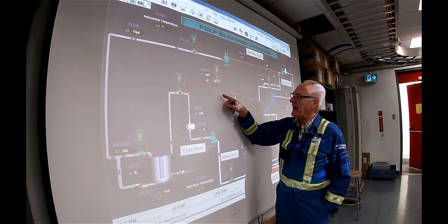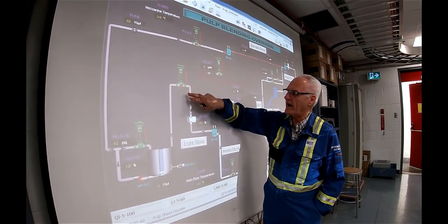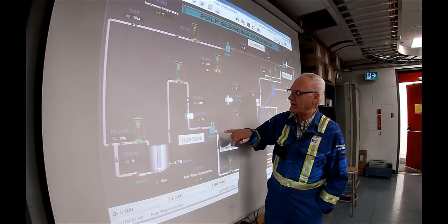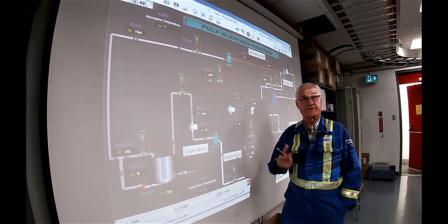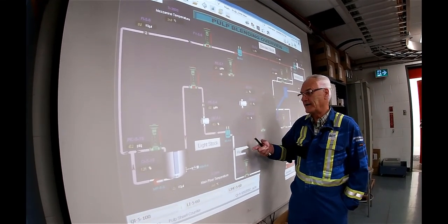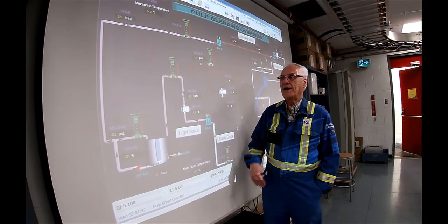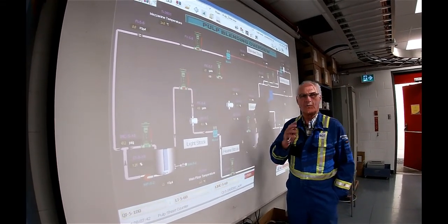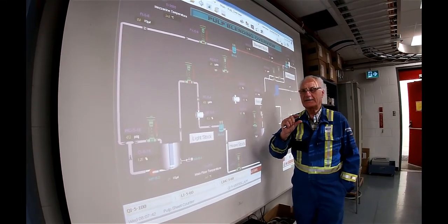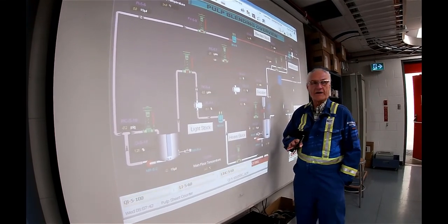Then they're going to open up a hand valve here and adjust this flow control valve a little bit more to get up to 75 gallons a minute. So we're putting in 37.5 gallons a minute of water and 37.5 gallons a minute of stock at about 3.5%, which is going to make pretty darn close to 1.75 here. Once the system's all loaded up, then this will all go on control. That's the little formula, and it's in the SOP exactly how to do that to get it roughly at the approximate consistency we want. Okay, that basically covers this part. Thank you.